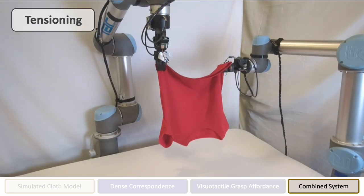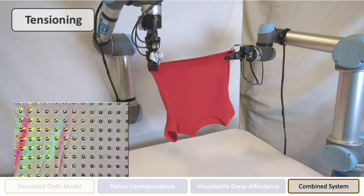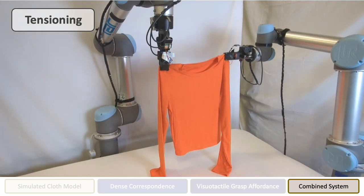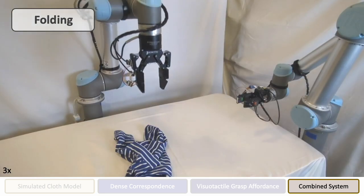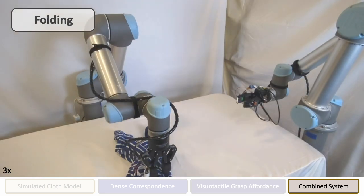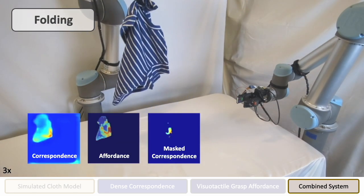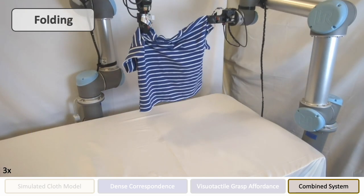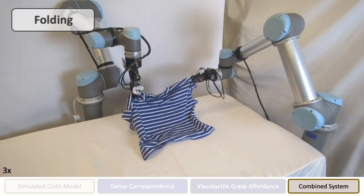We tension using tactile shear estimates by tracking the displacement of the markers on the gel surface of the fingertips. This closed-loop step is useful for generalizing manipulation to shirts of different sizes and to different grasp points on those shirts. Here's a full example of folding, where we show the tactile classifier after grasping from the ground. We show correspondence, affordance, and correspondence masked with affordance, tactile classification from the grasp attempt, tensioning, and folding.